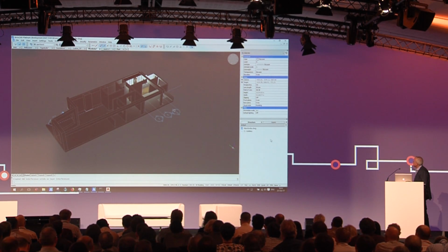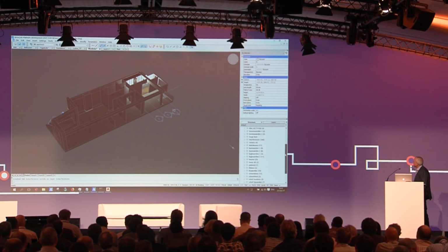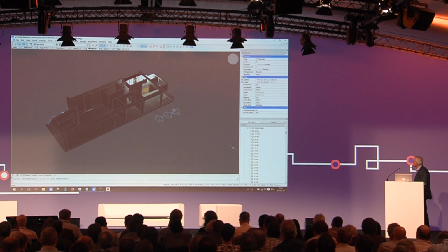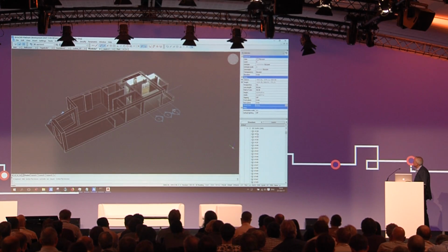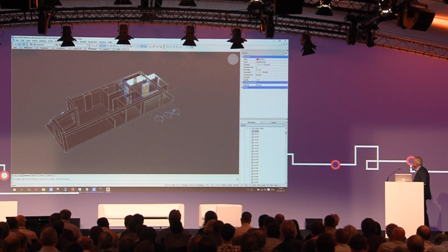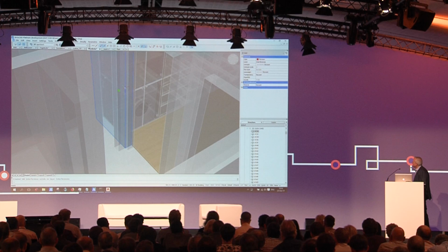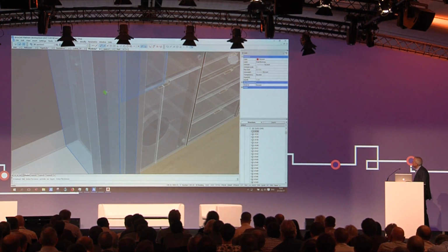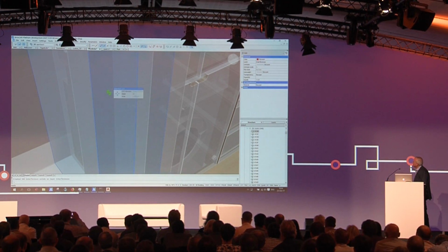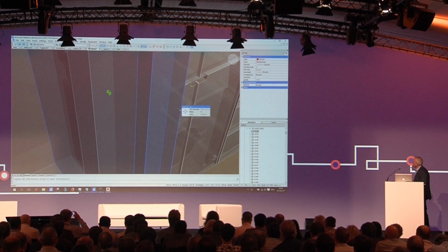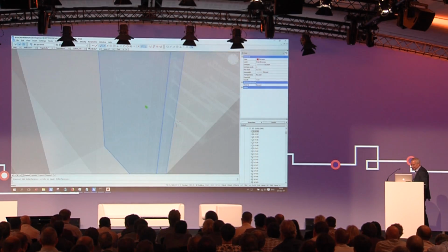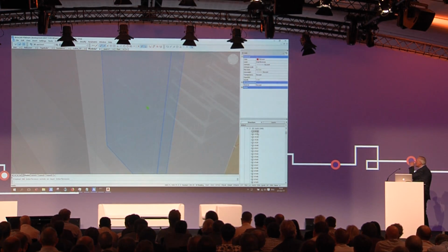So, and what would we use to do that? Well, the structure panel, of course. The interferences are grouped nicely together. So the first one is over there. And it's like a domino, it's a panel connector for 2 panels of the furniture, and it's apparently inside this wall, which is wrong.